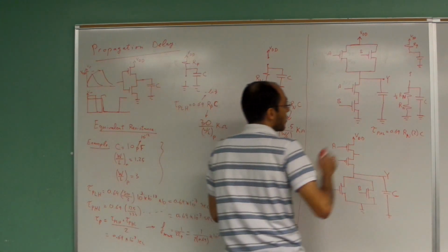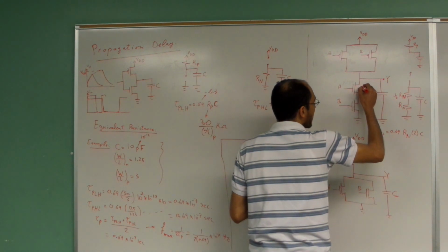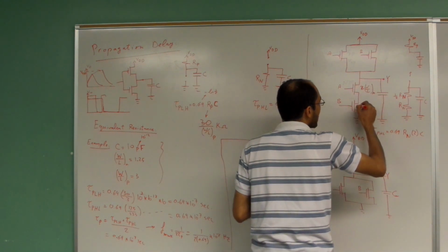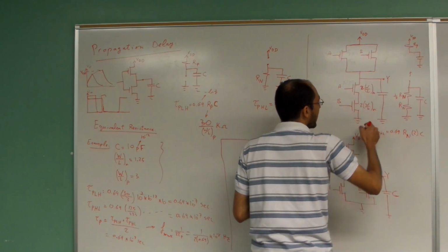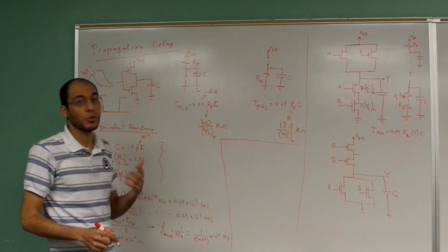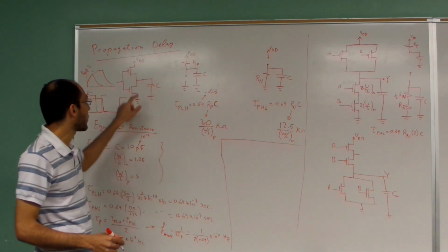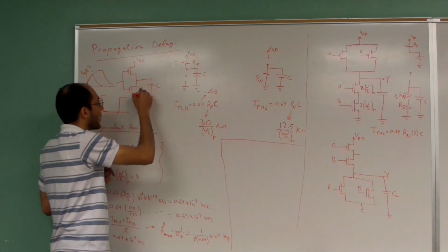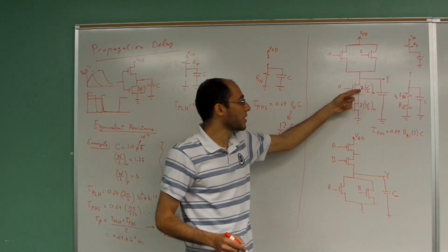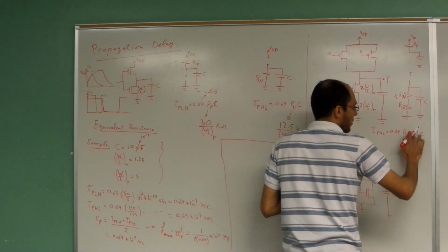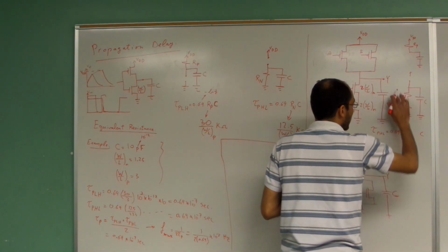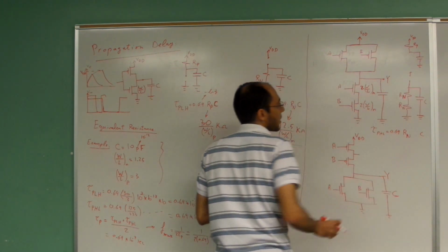And that is why sometimes we say this is twice W over L N, and this is twice W over L N. Why this two? W over L N refers to the ratio of the width over length of a regular MOSFET of a NOT gate, right? So we tend to double this by 2, and in that case, you do not expect to see this half, all right? You do not expect to see this half, right?